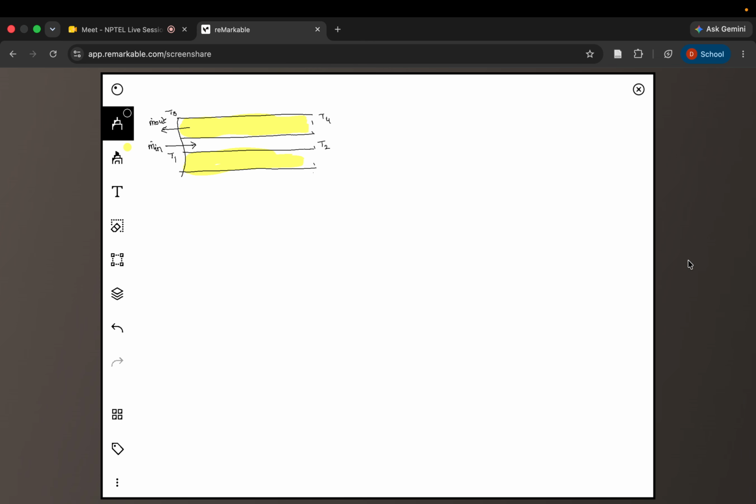So, whenever, even in assignments, the problems that you will be given are like this, where you have to apply, first, the mass conservation equation. We only have three conservation equations: mass, momentum, and energy. These are the only three equations that you will be using. And in this particular problem, whenever heat exchangers, etc. come, the momentum equation is not even used. We'll be only requiring mass and energy equations.